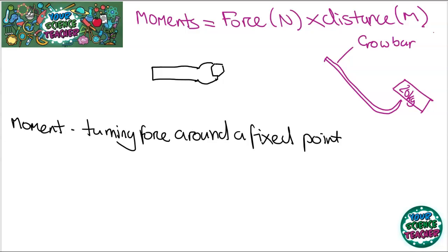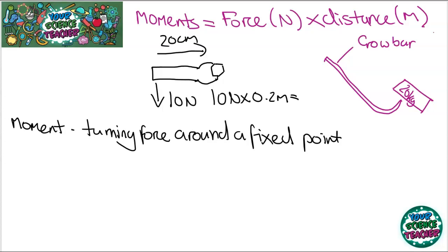Now, for a screwdriver, for example, maybe I'm applying a force of 10 newtons and this screwdriver could be 20 centimeters long. In order to calculate the moment of that force, I would have to do 10 newtons times 0.2 meters. Remember, moments are measured in Newton meters, and this will give me a moment of